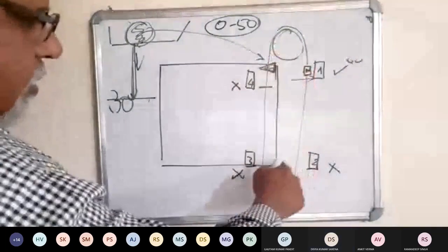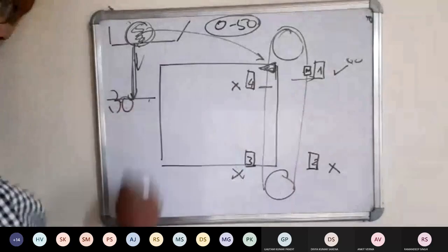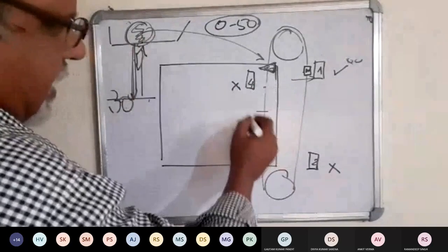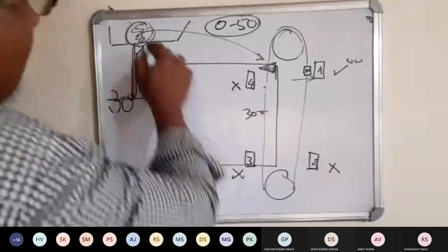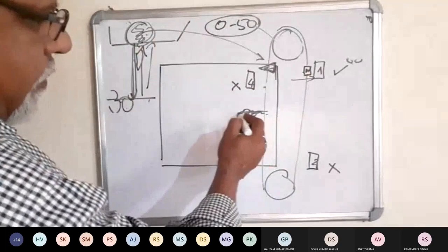That's exactly what I wanted to hear. Because it is running at half the speed. When this runs 30, this runs 15. When the signal goes back, this goes 15 further, and at 30 meters here, the received signal is given to the stylus, and the stylus makes a black mark here.